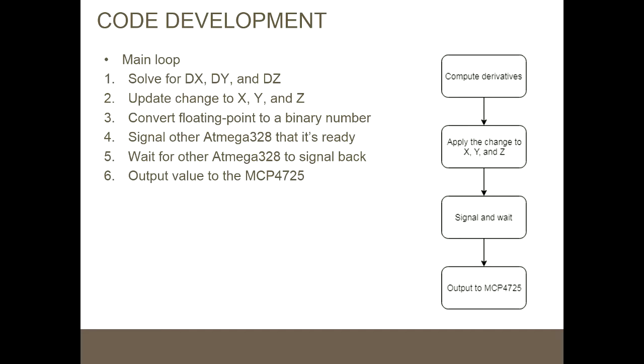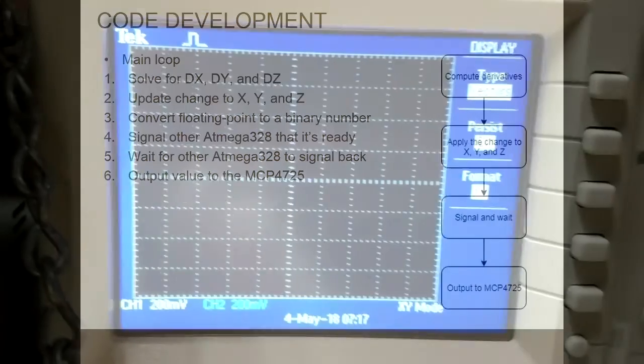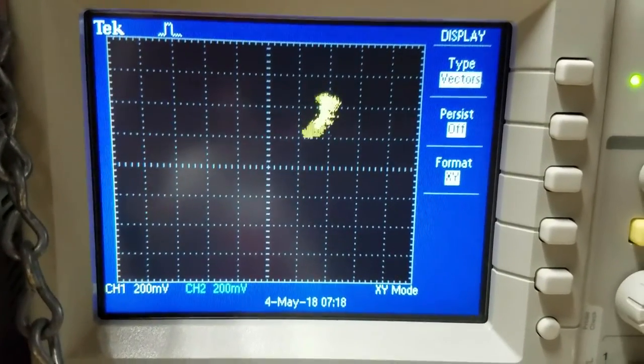You have to put it into some kind of way to interpret that data. So in my case, if I get something like 1.54 and so on, I just truncate the fractional part. You're left with the 1, and I scale it to some sort of number. For example, I multiply it by 32 in my project. The reason I multiply it by 32 is that when you run the test on whatever computer you have for the C code, you get numbers like 1.5, 1.6, 1.25, very small numbers that are not far apart, and you can't really distinguish them. So I just scaled them up, and eventually you get a number that is meaningful to the DAC.